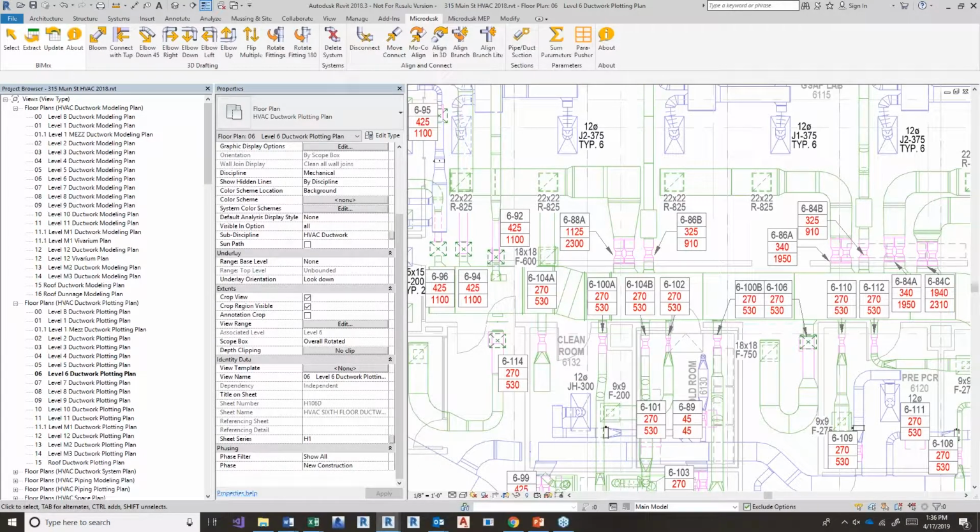Okay, so keep in mind that was an example where we received information from a third-party source, previously unrelated to the model, except that it shared a unique identifier for all of the major equipment. Furthermore, as a QA/QC effort, we could have used that lookup formula to identify cases where we got that NA, meaning that the lookup command didn't actually find the VAV box number in the list that we received from the commissioning agent or from the project engineer.